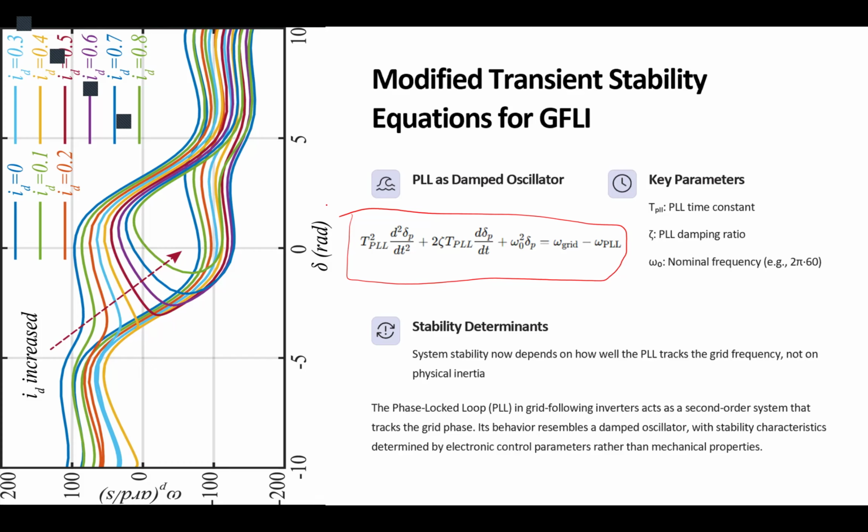More resistance to the change is the definition of inertia: the ability of the system to resist change. Okay, so now if we have a higher T, that means when any variation is injected into our system as an input, the system would react to that slower. That means the system is heavier, if you want to consider that as a physical system. So we have a higher inertia.